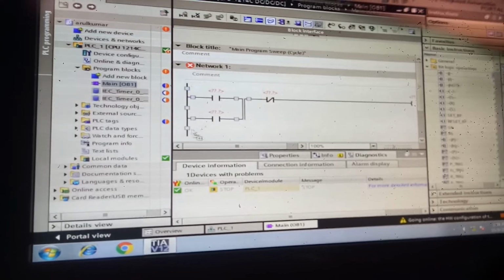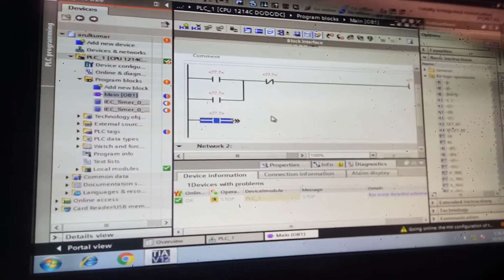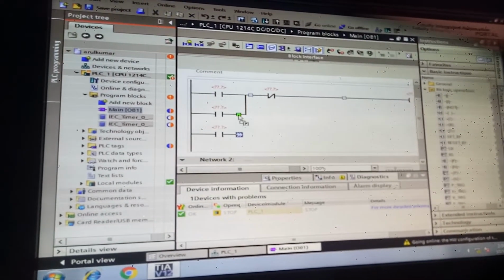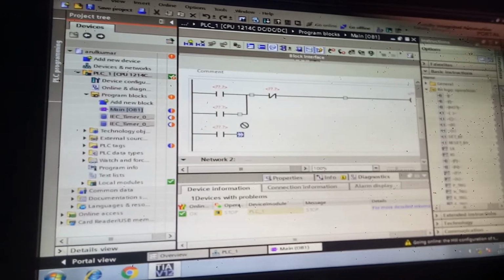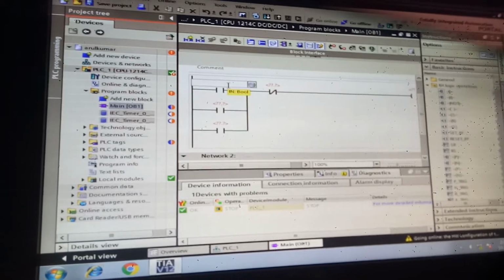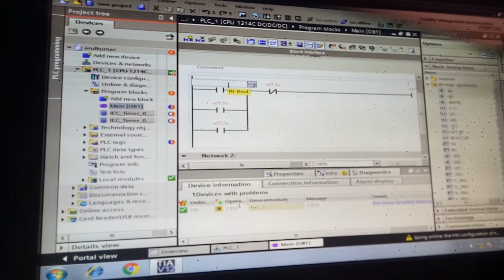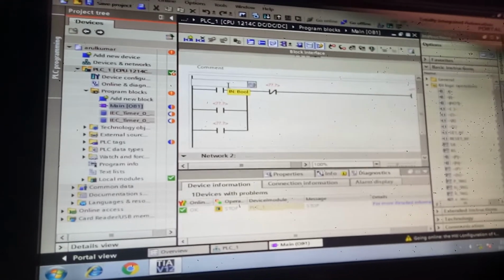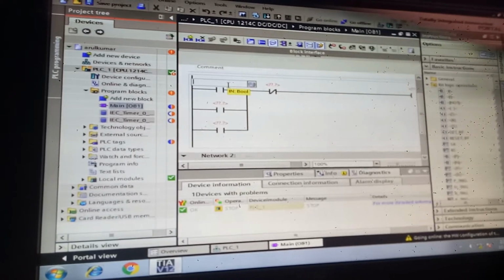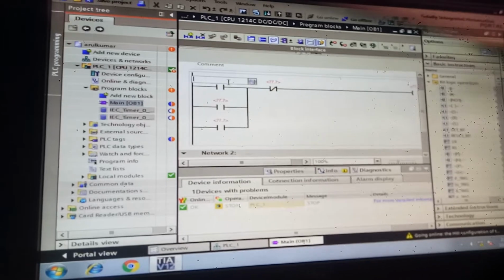So I go for drawing the ladder diagram for A plus B minus A minus. I'm going to use two double acting cylinders. Here we are latching. This arrow can be clicked and dragged over the upper one to get the latching. For naming, they have given I1, I2, Q1 like that, input and output. But in this PLC they mentioned 0.1, 0.0 like that.